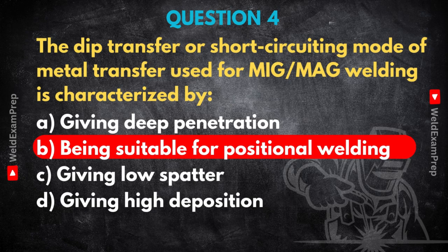That makes it great for welding vertical up or overhead or horizontally. You can manage the molten metal against gravity. So welding pipes in position or overhead structures? Perfect for that. Also good for thinner materials where you don't want too much heat and for bridging gaps.